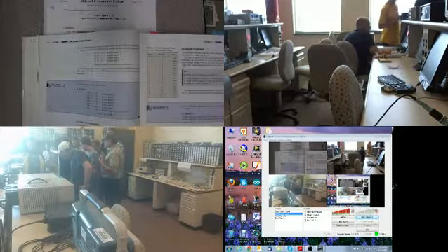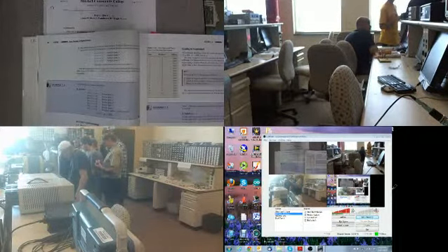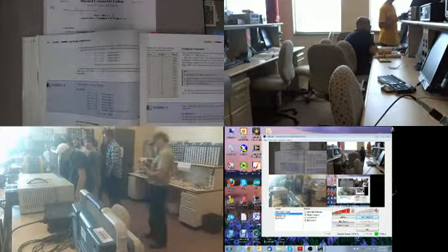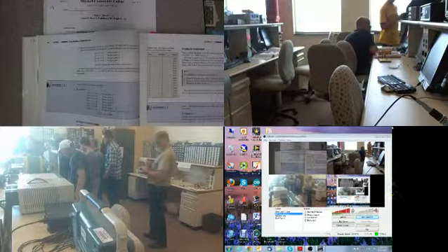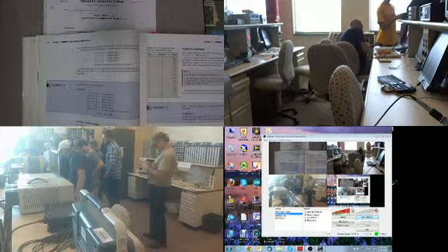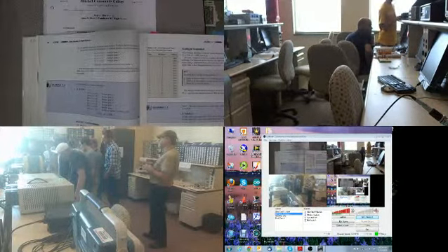See what I did right there? I'm making sure that the technician knows, because the technician is not going to have the data sheet. He's probably not going to want to look at the data sheet, right? So whoever's doing the design, the engineer, is going to put all the information that the technician needs in order to build the circuit. Typically you're going to have a drawing with all kinds of packages. You don't want the technician to have to go look up 20 different drawings. So this tells the technician pin 1, 2, 3. Now we'll just call this U1. We'll call it A. That's the designator part. So that's the check mark is done.